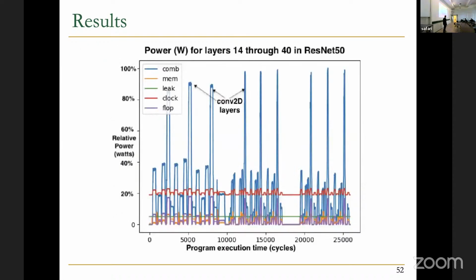Okay, another interesting thing is the power utilization. And you can see that it uses a lot of power where all of the units are used in these conventional 2D convolution layers for the ResNet-50. But in between these peaks, there is not that much power utilization. This is because they claim that the chip can deactivate superlanes that it does not use at the moment. So if you only have short vectors, so low amounts of data, like you only need one of these 20 superlanes, it can actually deactivate the other 19 superlanes in the meantime. And so it should be really scalable and power efficient.